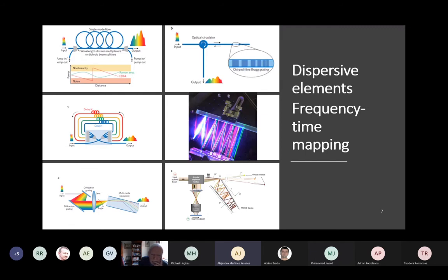On the middle left, a different approach is a recirculating photonic filter using an arrayed waveguide grating in which an arbitrary delay is applied to each channel. So you can manage the dispersion by managing the delay of each fiber. And now we can classify the next methods as the ones that allow mapping into the 800 nanometer band or visible bands. On the bottom left, spectral to angular temporal mapping.